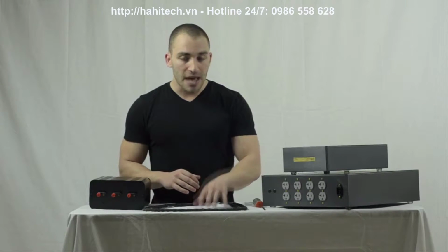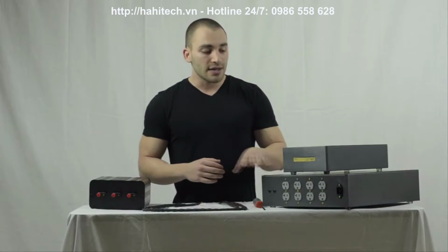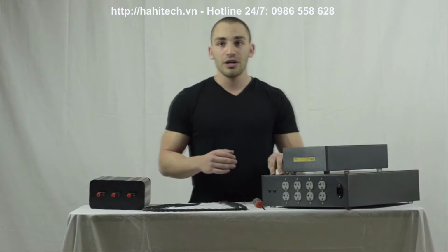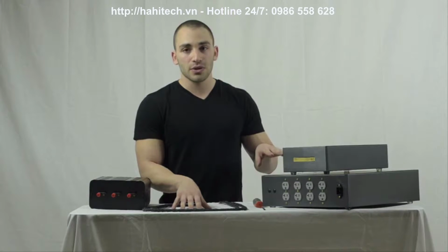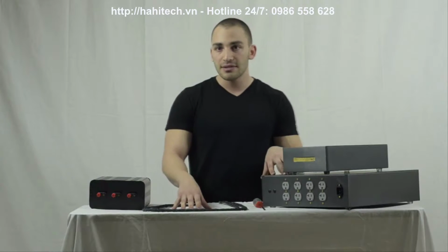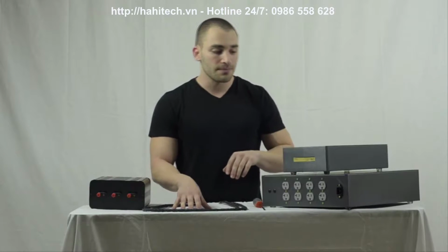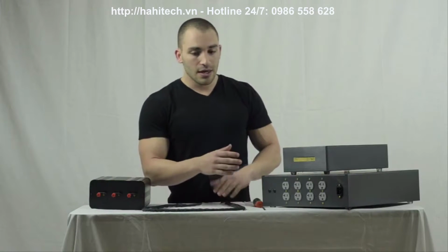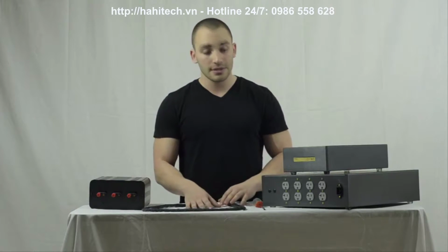One of the best recommendations I can give you in terms of grounding your audio system is actually a little bit against what you'll hear in a lot of audio forums: you actually want to have your entire audio system grounded to a single receptacle. And that will help to eliminate any of those common impedance issues that you'll face when you have voltage differences between all of the different receptacles. Those voltage differences can be anywhere from a couple of millivolts to over a volt, and the larger it is, obviously the worse a ground loop you're going to experience.